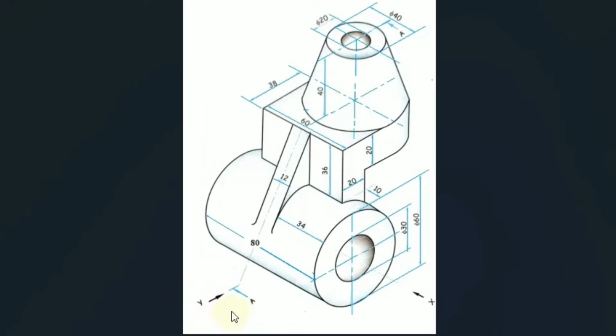But apart from that, you can see here different arrows have been shown for direction A. Of course, the direction is the same as that of X, but why is it shown on this axis line? Because we are going to cut this object along this axis line. So the whole object will be split into two equal parts, and then the part which is nearer to the observer will be removed. And then the retained part we are going to view in the direction of A itself.